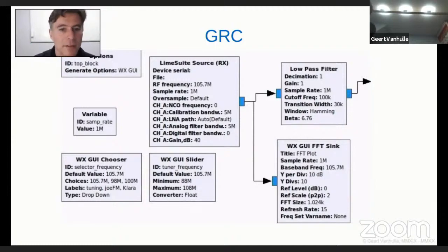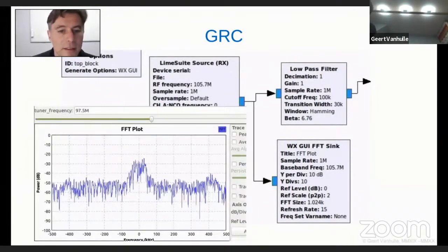So I have this 1 megasample sample rate stream of samples going out of my hardware here into my flow graph. And the first thing I will do is put these samples to a processing block, and this is a fast Fourier transform processing block. So we will do mathematically a fast Fourier transform that will take our sample series, which is a time domain series, into a visualization in the frequency domain. If we do so, this is the result.